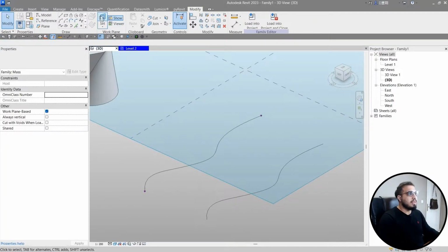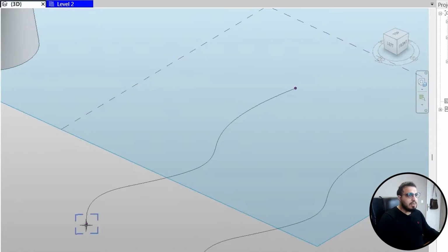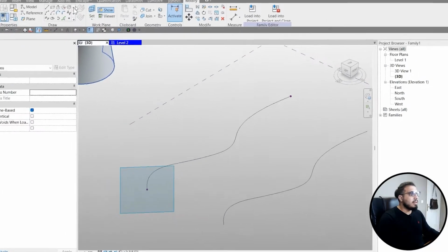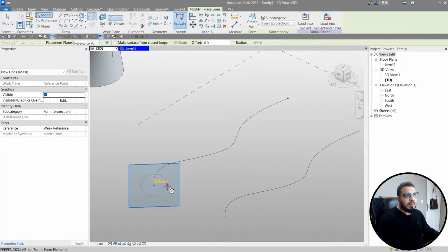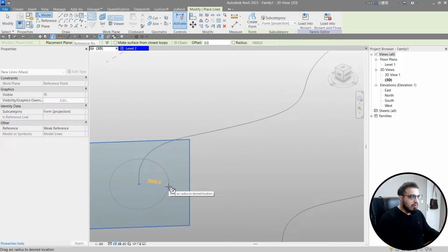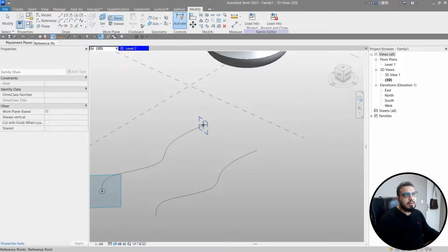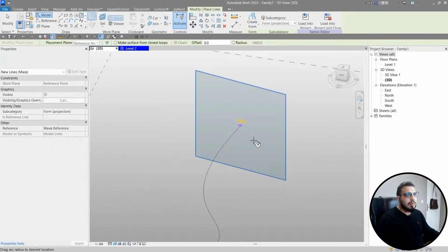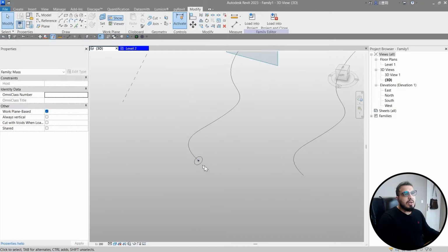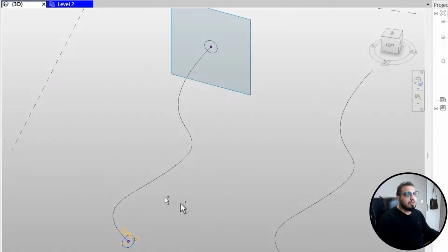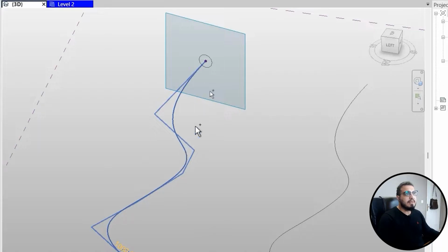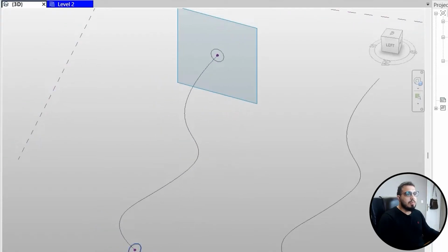You need to click on set and go on the points, and in here you can see we have a face in here. Click on it and set your work plane on this, and again let's create a circle in here, maybe with the dimension of maybe 1000. Also again let's set our work plane on this side. Let's create another circle at top of this point with 1000 units. And now let's select all of the circles and all of the profiles and the path. The order is not that important. You can select this and this and this, or you can do the reverse.